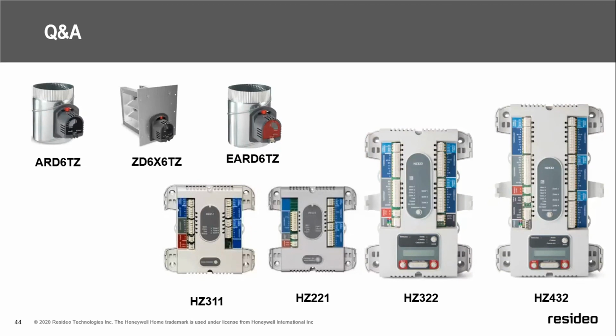We typically ask you not to go beyond 5 tons on our zoning systems using the CPRD bypass damper, but it has a phenomenal capability of giving the back pressure that the variable speed motors so desperately want to operate with good manners in a zoning system.